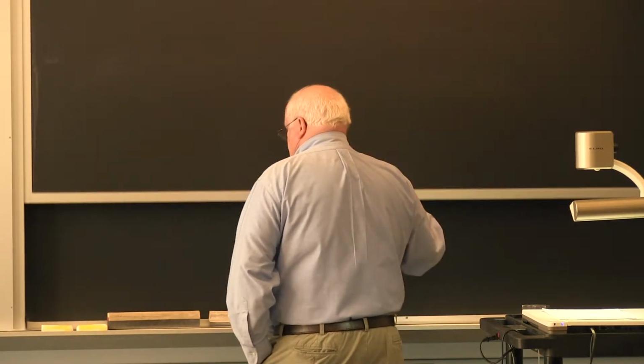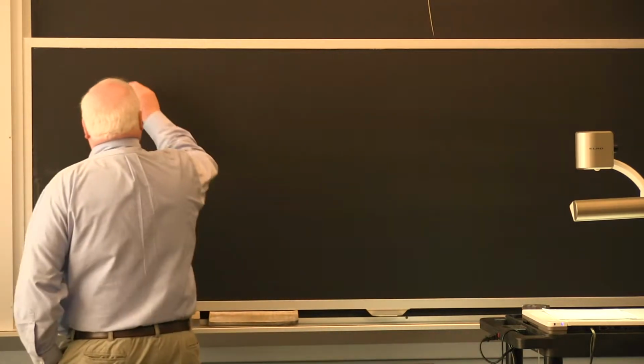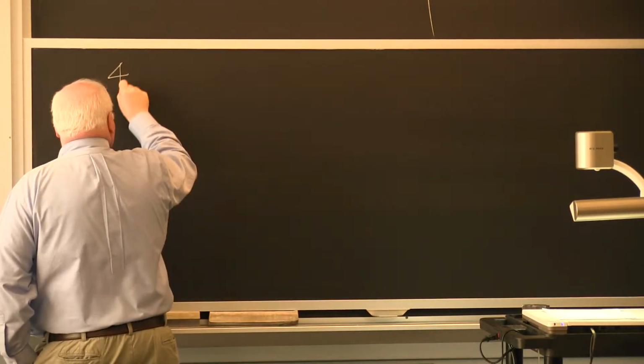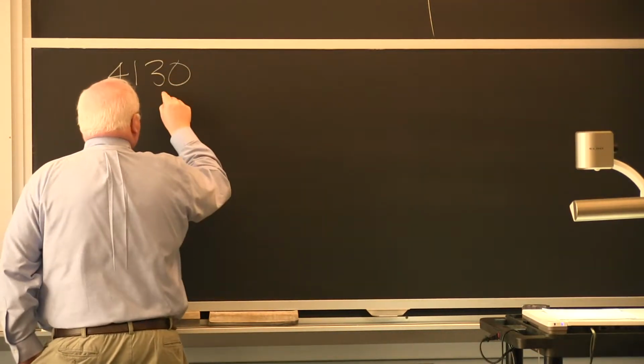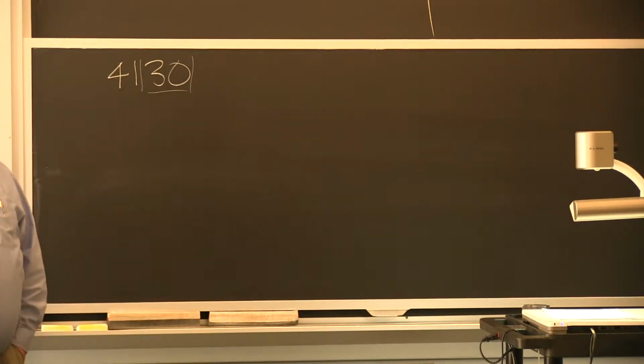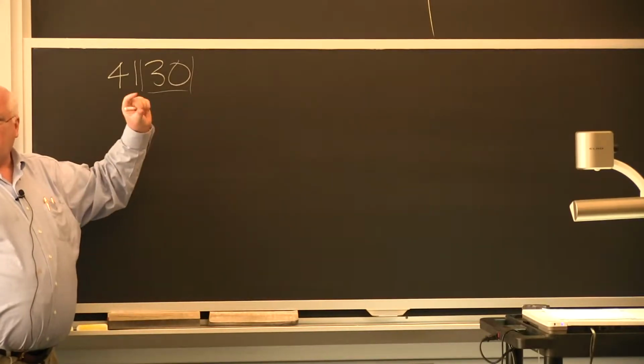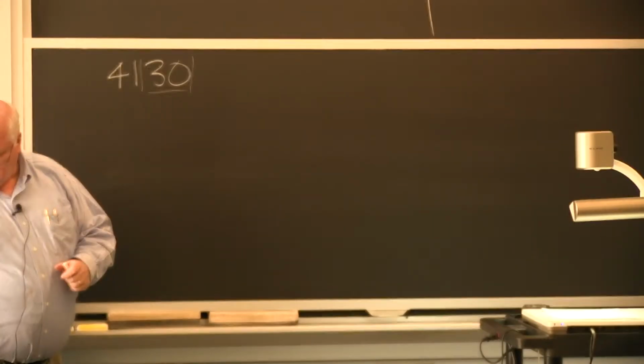Now, 4130 steel is also used for things sometimes called aircraft tubing, okay? 4130, the 30 tells you I got 0.3 carbon plus or minus about 0.04 or so. So it could be 0.26 to 0.34 carbon, because they can't hit it perfectly at the steel mill every time.